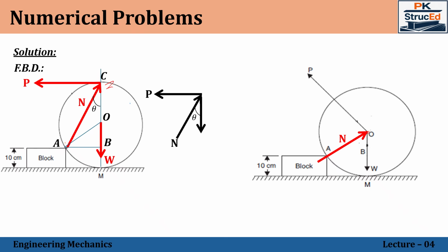So if you know this simple concept, where the instantaneous center of rotation will be taking place with respect to that point, then the reaction from the contact points will be directed accordingly. If you know this one, later, resolving the forces and applying the equilibrium equations, we can solve for the unknowns.